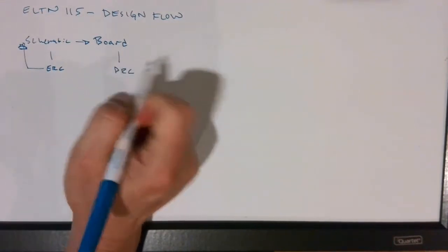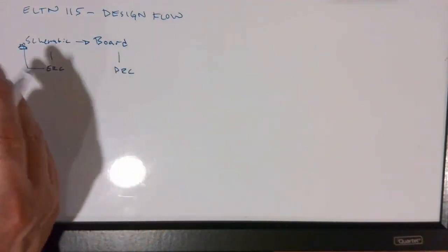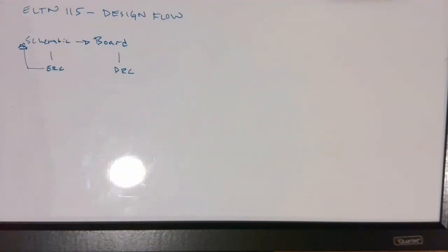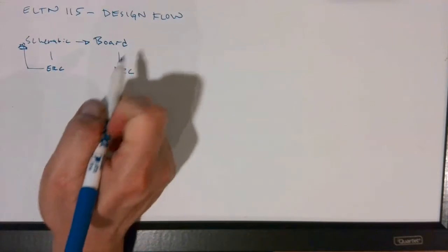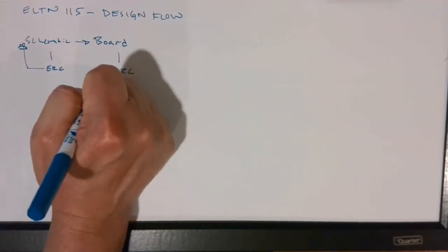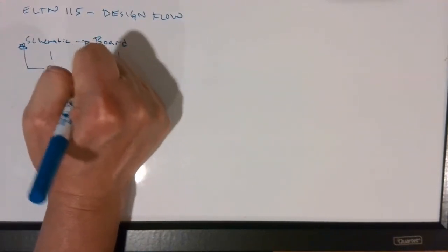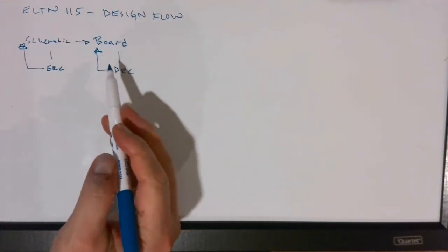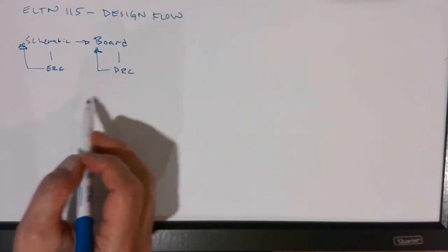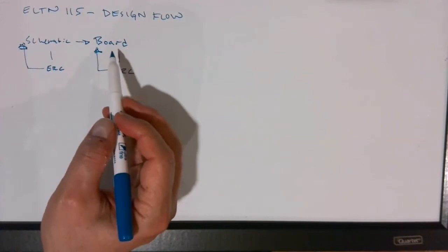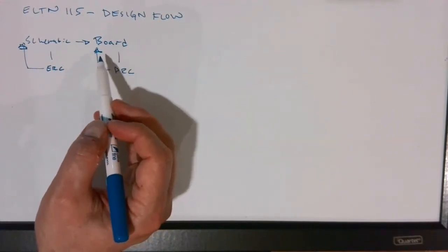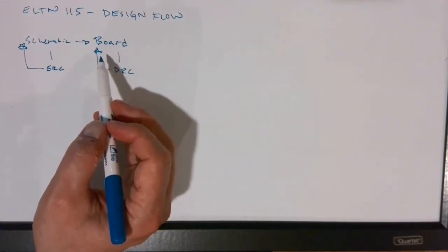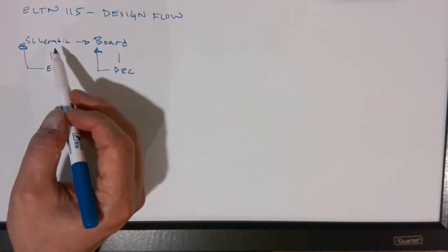So it's not just a one-person job. Usually if you're designing a circuit board, you're working with other people to find out what the criteria are. But the idea, again, is that you go through a process of design checks. At some point, you might even have to loop all the way back to the schematic in case, for example, a component isn't the right component or is the wrong size. You might need to modify that in the schematic.